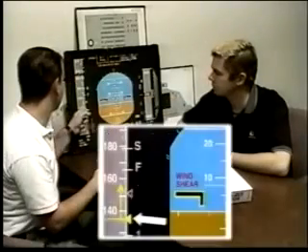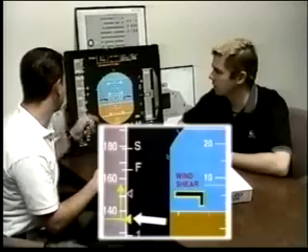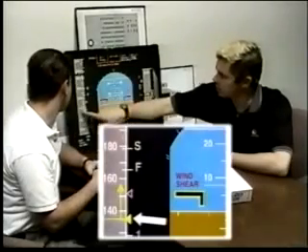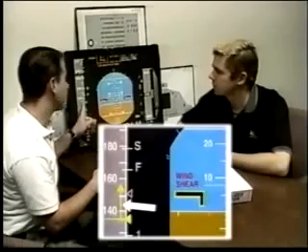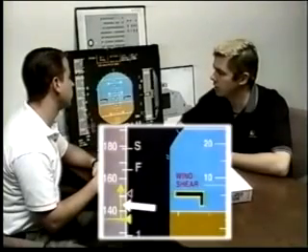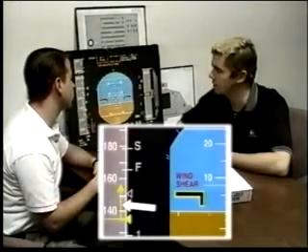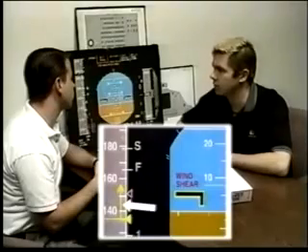Okay. On to the horizontal yellow line. What is that? That indicates on the tape itself the speed that we're actually doing right now. And the vertical yellow arrow? That's called our speed trend arrow. It indicates the speed that will be in 10 seconds if everything remains constant.